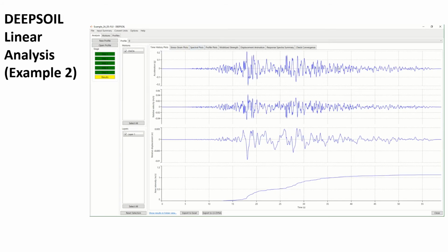The acceleration, velocity and displacement time histories are a bit more realistic, and this could be the value recorded on top of the soil surface after the interaction between the seismic wave and the soil profile. So you can now understand that having an elastic bedrock will dissipate quite a lot of energy, and it wouldn't lead to the resonance phenomenon that we've seen before.